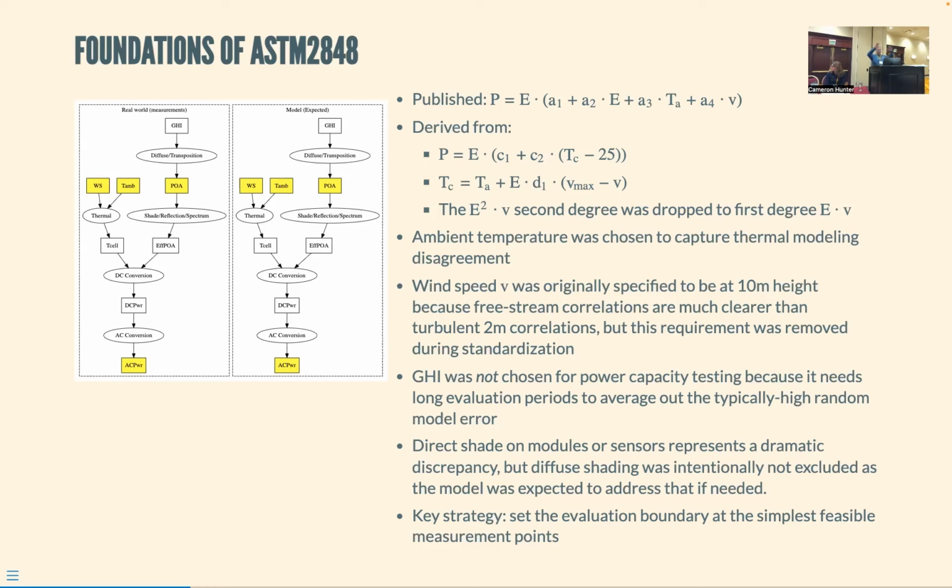You could have a continuous cloudy sky. You could have a bright spot over here. They have very different diffuse light behavior that, when you tilt it up, gives you a different answer. So transposition is a very imprecise thing.